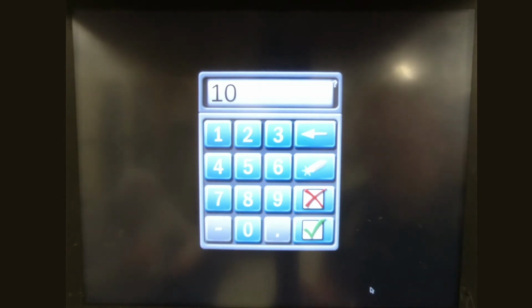The headroom percentage is a buffer for the ACO rate control valves. The rate control valves split the hydraulic oil between bin 1 and bin 2. These valves are located before our newly installed proportional flow valves. The buffer allows us to maintain the product rates. If the algorithm doesn't call for enough flow, this buffer will compensate to allow Engage SpreadControl to stay on the desired rate.